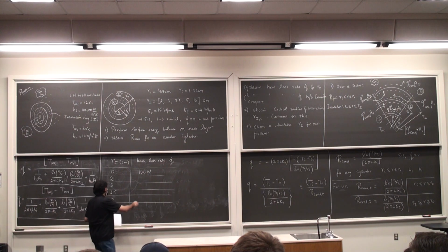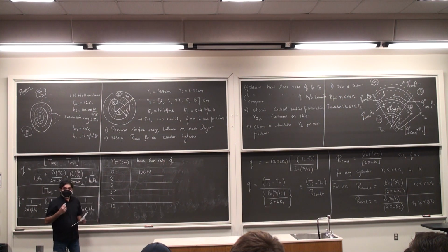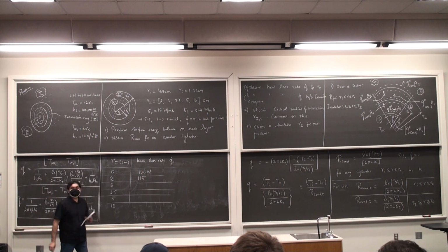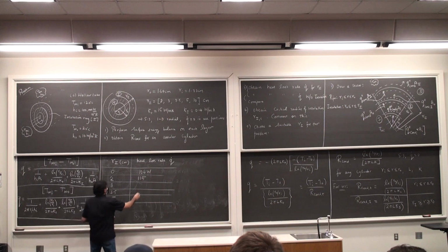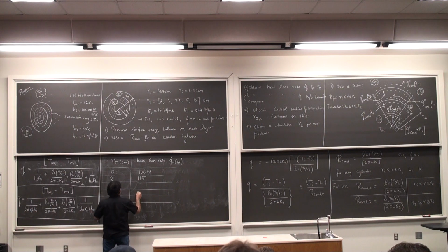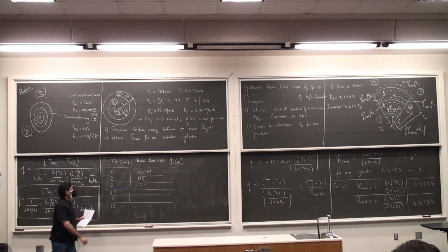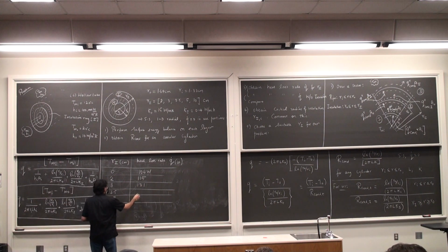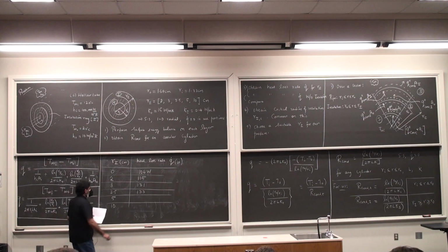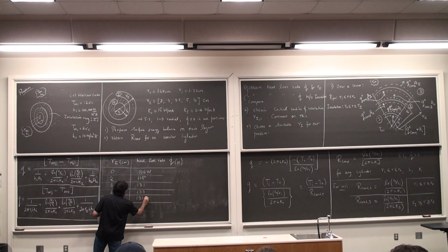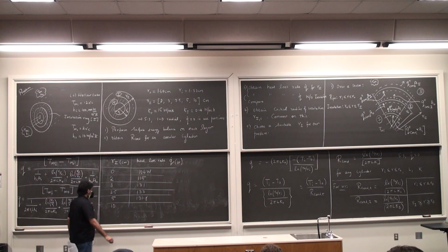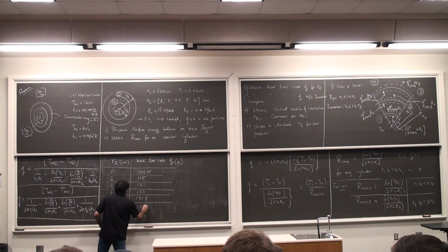Okay? So as you increase the radius of insulation, here is the funny thing. The heat loss actually starts increasing. This is all in watts, goes to a value of 131 when I hit 3 centimeters of insulation thickness, radius, 133, then I come to 132 or 131.8, then when I come to a radius of 10 centimeters, 105.